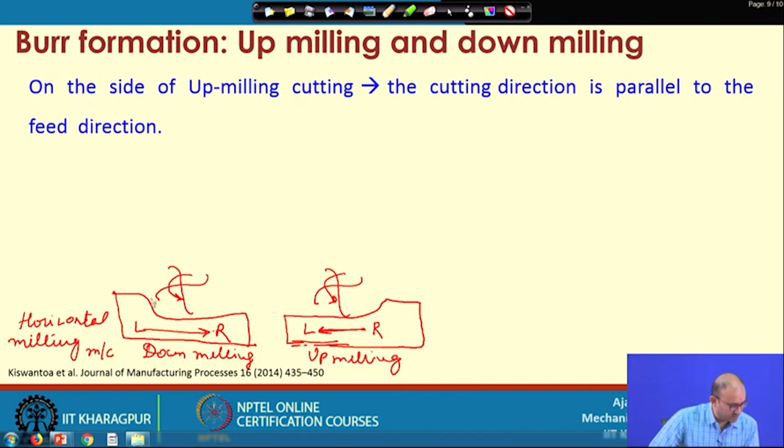So, in this case if you consider this part, how can you name this down milling? Because your cutter is moving in the downward direction with respect to the top surface of the workpiece. Now, this is the top surface and this is the machined surface by means of this milling cutter, and in this particular case with respect to this top surface your cutter is moving upside in this direction, that is why it is called the up milling process.